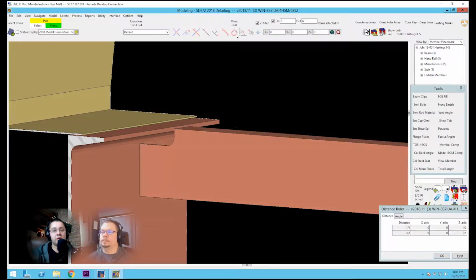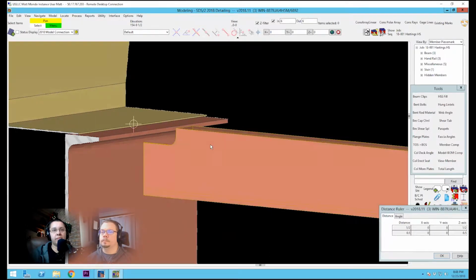So what you want to do once you get into this dialog box, so remember the points that you click the first time that you apply it, and hit that save button at the top of the dialog box. Save all of your entries into that dialog box, and then just use those over again and apply them again. Don't try to copy the component from one to the next because it will mess around with the reference points and everything will be off slightly. Don't ask me how I learned that lesson, because it'll look good. You'll think you have it, but in reality, everything is jiggered by a 16th or an 8th or something like that. So, all right, so we'll show you how to do this.